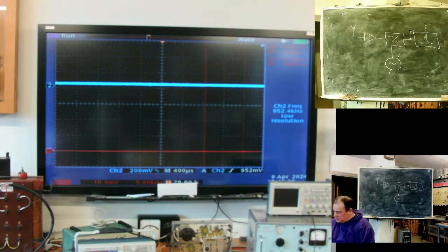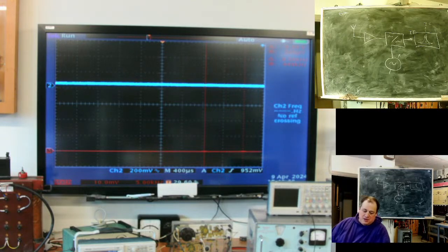Relatively small models also exist, but super long range or military intelligence receivers are built with triple conversion and a triple set of selective networks and an extremely carefully created heterodyne, because frequency stability depends on the stability of the first heterodyne.